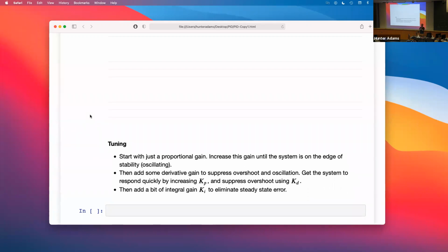The P term of the PID controller just scales that by whatever KP is. It'll probably start with 100, right? The I part adds that current error that you've just measured to a variable that's accumulating the sum of those measurements over a period of time and scaling that.